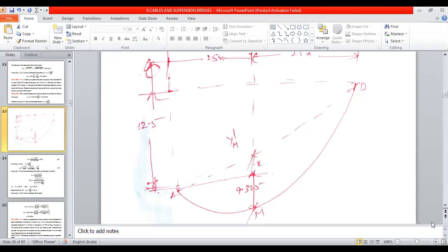So in such types of aerial ropeways or unstiffened suspension bridges, the load exerted by the trolley on the suspension cable constitutes a concentrated load. So the cable is generally subjected to a series of concentrated loads. Therefore, the shape of the cable changes slightly from position to position of the trolley. So, however, this may be a practical problem; there could be any practical problems with movement of the trolley.